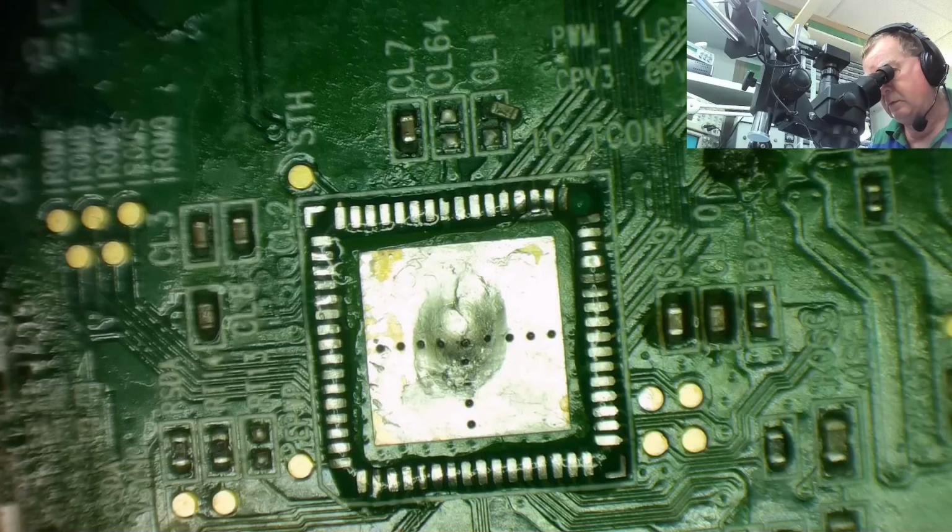So basically I want to add leaded solder to everything under here, all these legs, ready to solder on them. I'm now ending up with rather a lot in the middle, but we can get that off afterwards, that's not a problem. And every single leg, every single pad, I want ready to solder on. Okay. I've just knocked another capacitor off, I might have done. Not a problem, we can replace them.